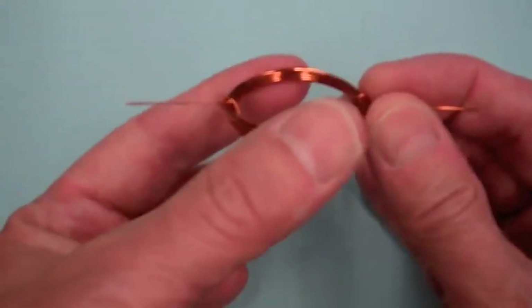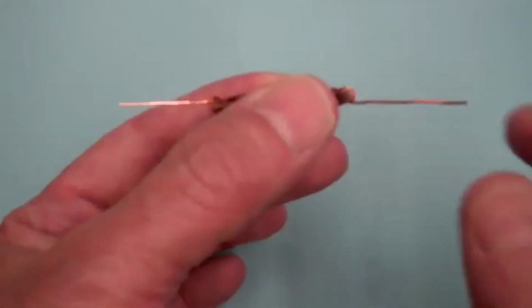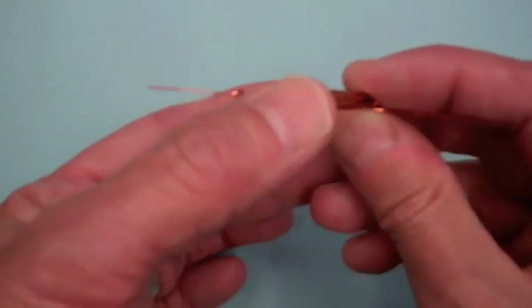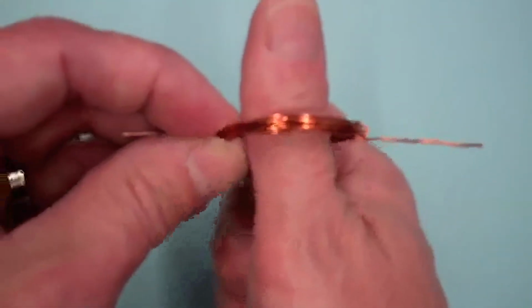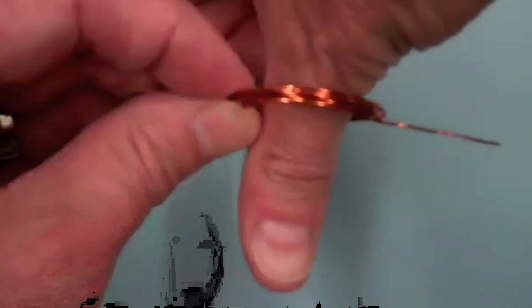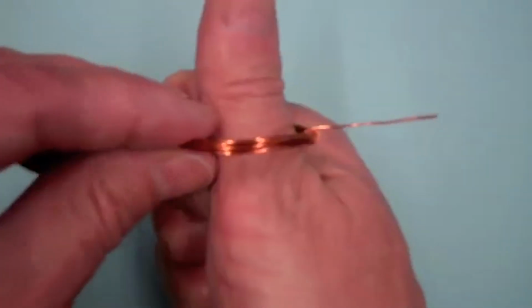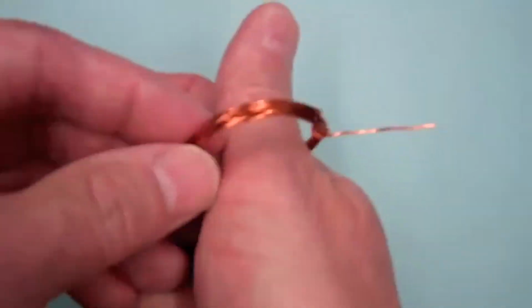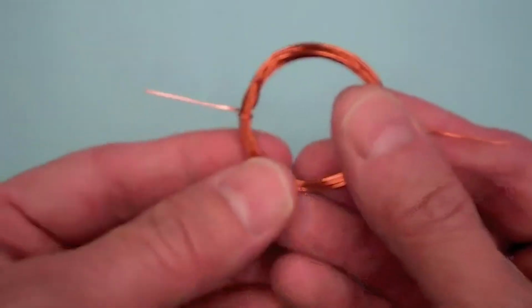But what happens in a motor is something called commutation. So at that point, the direction of current is reversed through the loop. So the magnetic dipole moment flips, and so again you have a torque which will rotate the loop until it lines up again. The current through the loop switches, and so that's why you get continuous rotation.